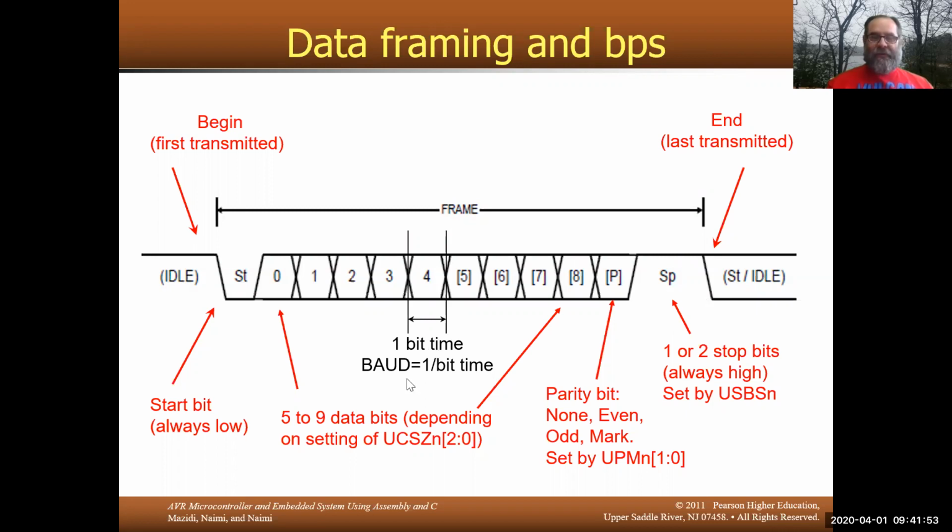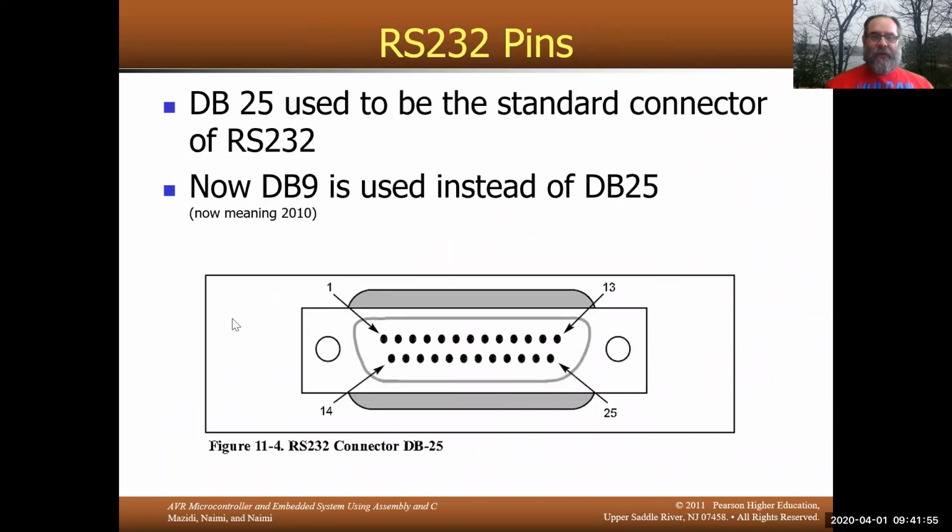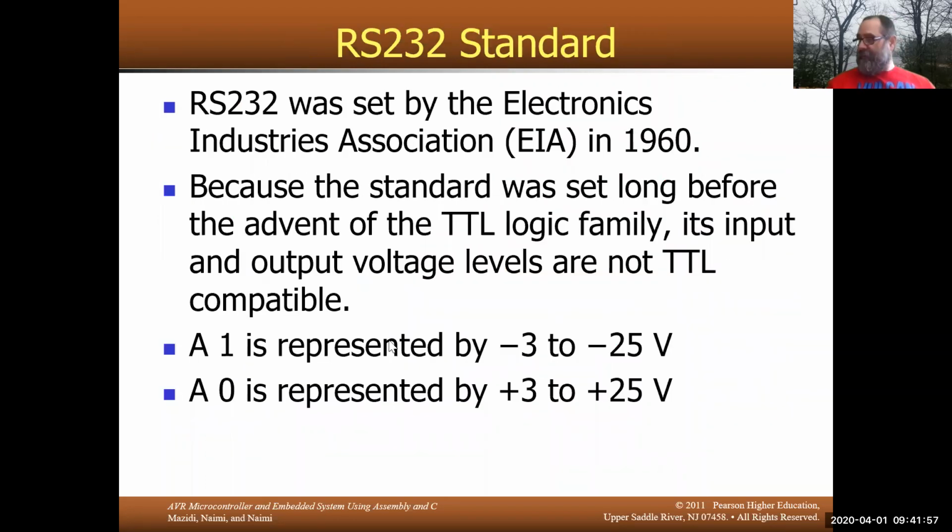And common baud rates, in RS-232. I repeat this because if you're doing a design project a couple of years from now, and you're connecting real RS-232 equipment, you want to be very careful. Logical 1 in TTL is represented by 5 volts.